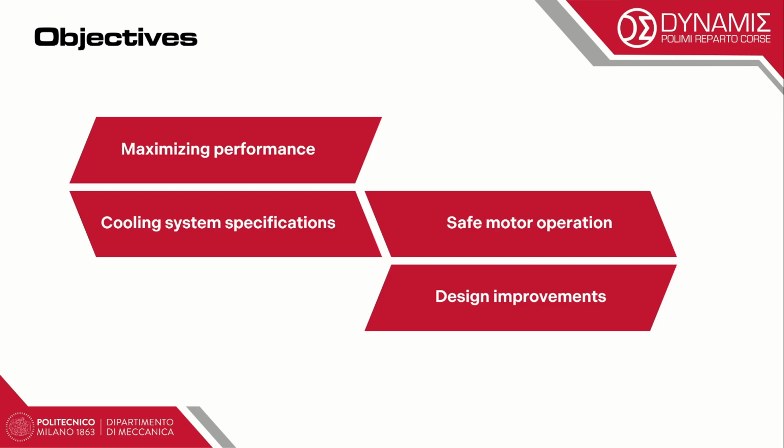What are the objectives of this thermal model? First, maximizing the performance of the vehicle by exploiting the motor's thermal characteristics. Second, determining the specifications of cooling required from other components of the cooling system and the motor's effect on them. Third, keeping the motor in a safe operation range and preventing adjacent components from thermal damage. And lastly, improving the overall design by identifying bottlenecks.